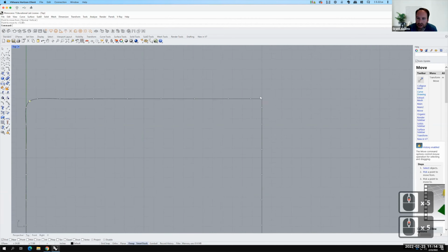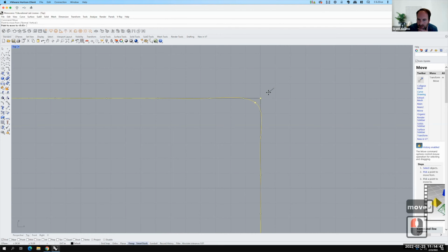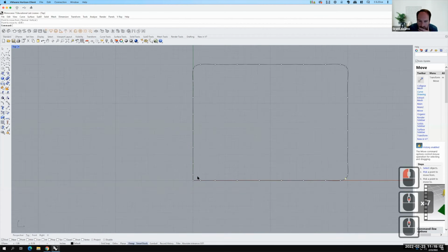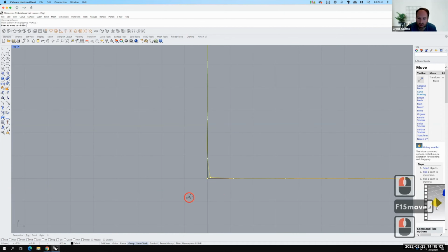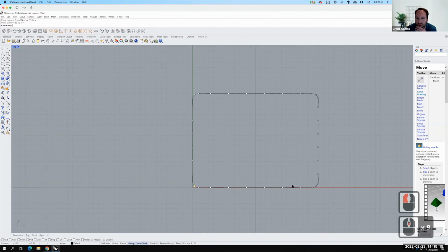And you guys are going to spend a lot more time now that you're creating this looking at what real cushions do. So you're going to go home and look at your couch and say, what does this really look like? Because a lot of learning how to model these organic shapes is observing the world. So let me take this one. I'm going to move this. We'll soften that up a little bit. Now, if you didn't want the corners to be this soft, you could rebuild the curves at a higher level than 10. So I could rebuild at 20, and the curve wouldn't be as rounded for these cushions. For our purposes, they're reasonable.